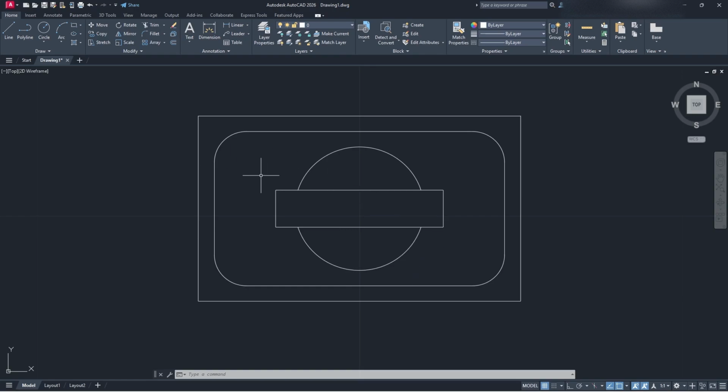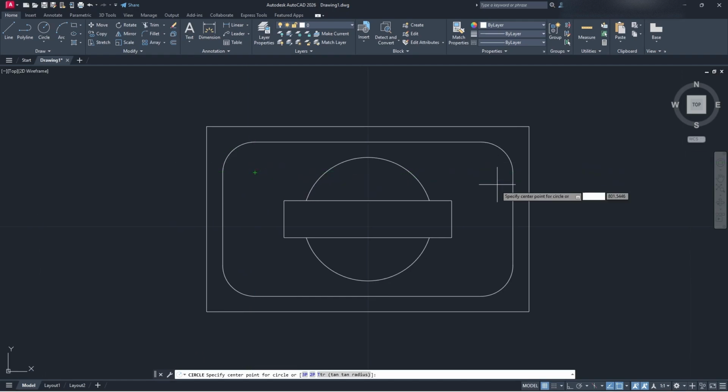And then what we're going to do is create some little holes in these corners here. The big portion of the hole has a radius of 1. So this part actually here, the center of this circle. You can see that I can still snap to the center of these circles. I'm just going to highlight those there. This is exactly where we need it to be, because these little screw holes or whatever they are are going to go in the center of our large circle here.